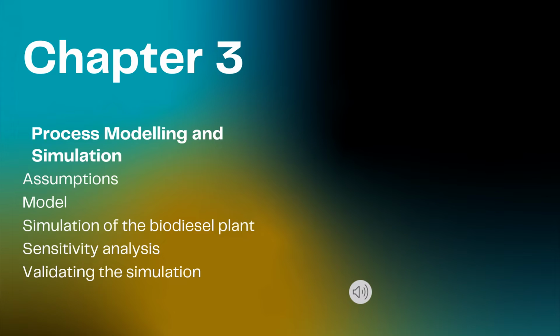Let's look into the process modeling simulation part. It is generally a reactive system and flows in steady state throughout the process. The rate law for this reaction follows the elementary reaction, where methanol is in excess in the reaction, so it follows a pseudo-first-order reaction as well. In this simulation, the catalyst used was sodium hydroxide, and the assumptions are that the suggested reactors are cylindrical in shape with constant volume.